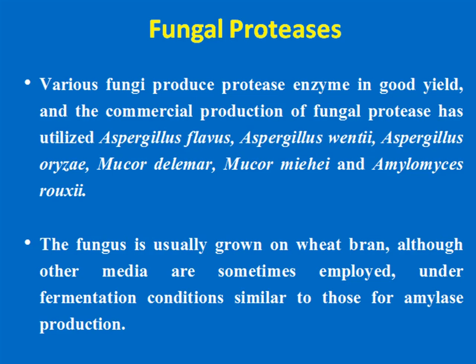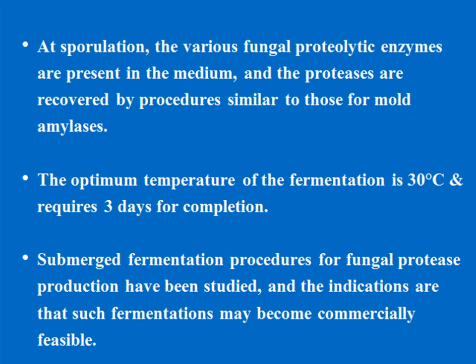The fungus is usually grown on wheat bran, although other media are sometimes employed under fermentation conditions similar to those for amylase production. At sporulation, the various fungal proteolytic enzymes are present in the medium, and the proteases are recovered by procedures similar to those for mold amylases. The optimum temperature of the fermentation is 30 degrees centigrade and requires 3 days for completion.